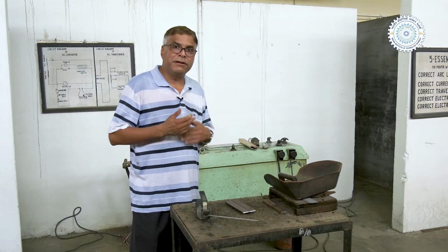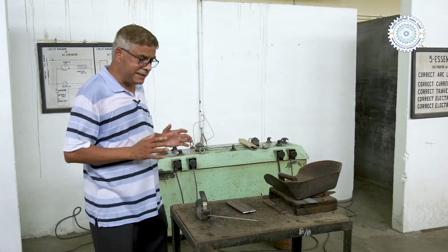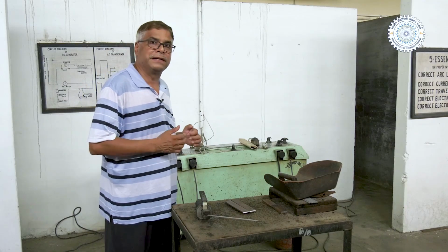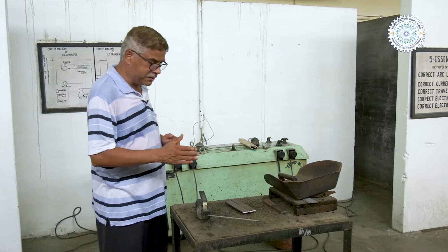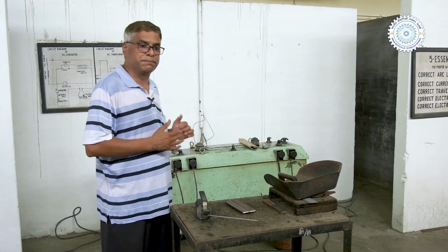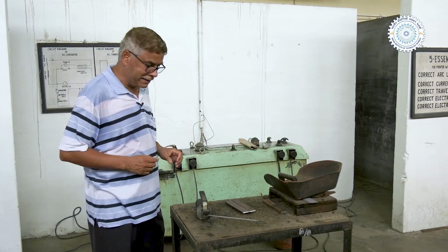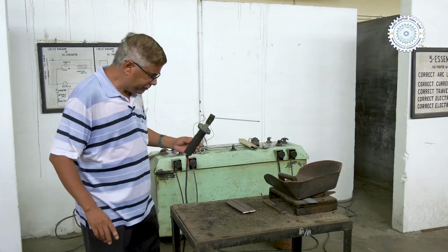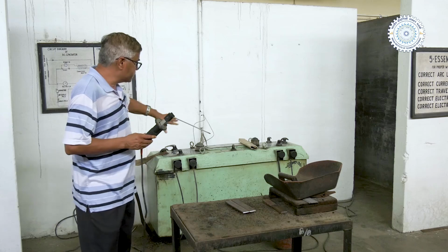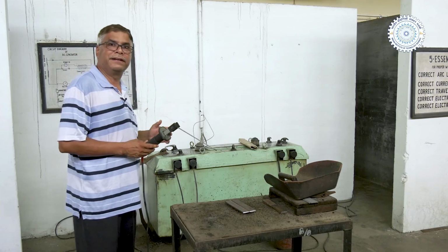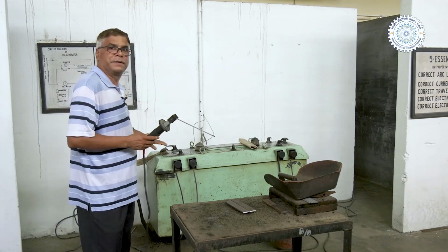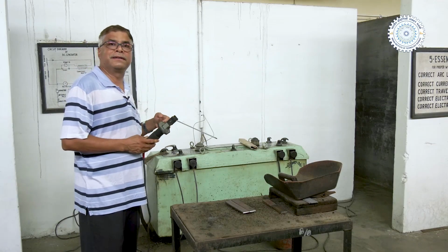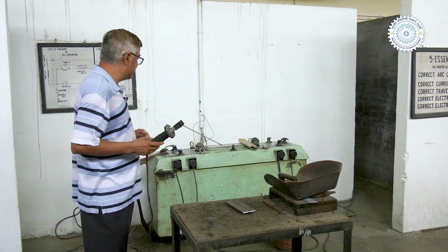So, the most important thing here is to develop the arc so that heat can be generated in a very controlled way in order to realize the true thickness penetration during the welding. So, how is the arc generated? Say there is a power source for shielded metal arc welding. Mostly we use the transformers for AC, and the rectifiers and the generators for the DC welding.